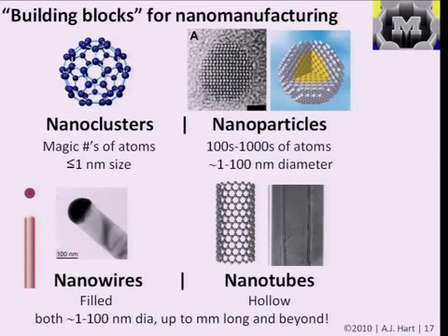And in the nomenclature down here, the distinction between a nanowire and a nanotube is just that one is filled and one is hollow. And there are some materials in which you can make both nanotubes and nanowires, and there are other materials that, because of their crystal structure, you typically make nanowires, and others that you typically make nanotubes. For example, graphitic carbon wants to be sheets, so you're more likely to make a tube of carbon rather than a solid wire of carbon. Silicon wants to be a three-dimensional crystal, so you're more likely to make a silicon nanowire rather than a silicon nanotube. Or you might have to use some more interesting strategies to maybe cut out the center of the silicon nanowire if you wanted to make a tube, and we'll see some cases of that as we move forward.